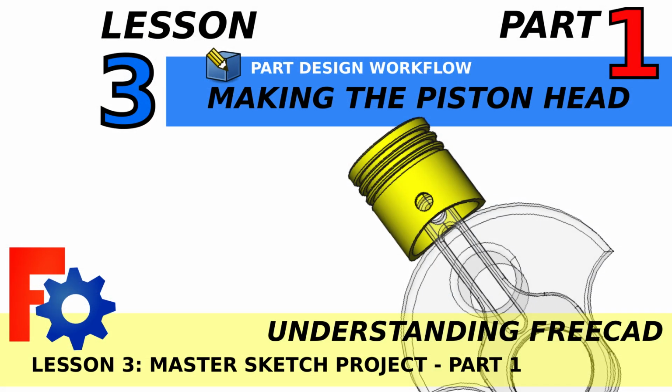So in video 1 we're looking at creating the master sketch. Now the master sketch will contain a very simplified version of the piston head, the connecting rod and the crankshaft at its lowest position, so all connected together. In the same video we'll learn how to create a piston head using revolves, using datum planes and learning how to position grooves and holes in that piston head so they line up with the rest of the assembly.